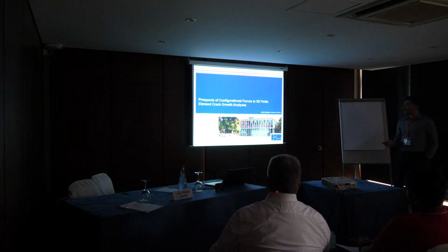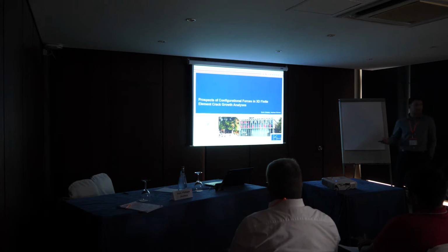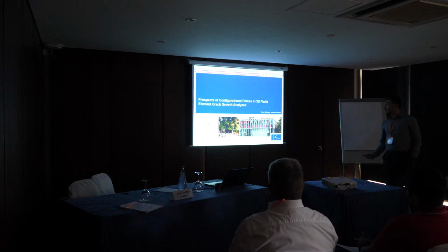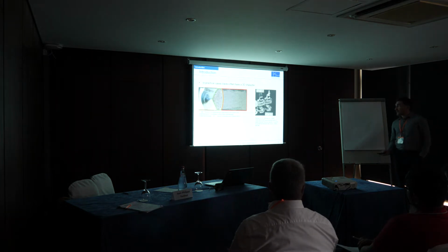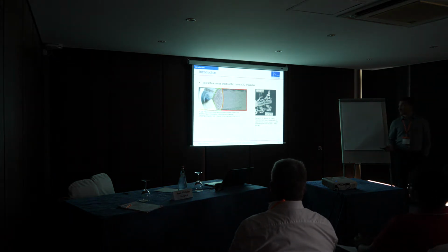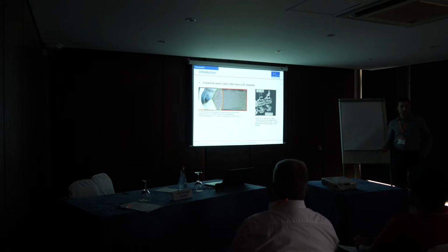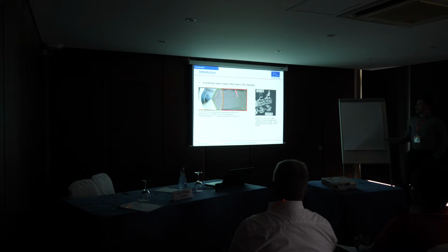And today my talk will be about the prospects of configuration forces in 3D finite element crack growth analysis. As you may know, in practical cases, cracks often have a three-dimensional character, meaning that spatial stress states can lead to very complex shapes of crack growth. This results in curved crack fronts, even for pure tensile loading, and when mixed mode loading is present, additionally crack deflection and twisting of the crack front can occur.